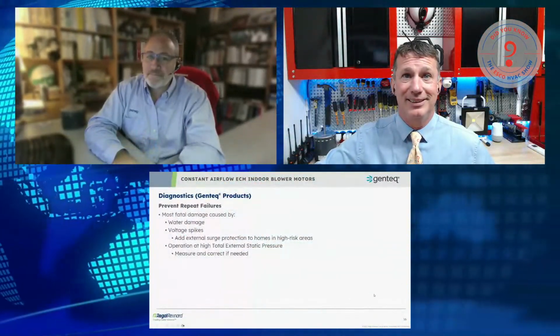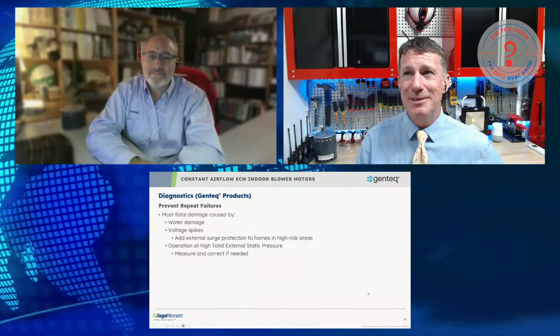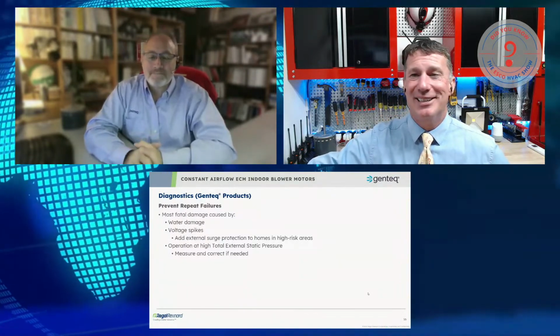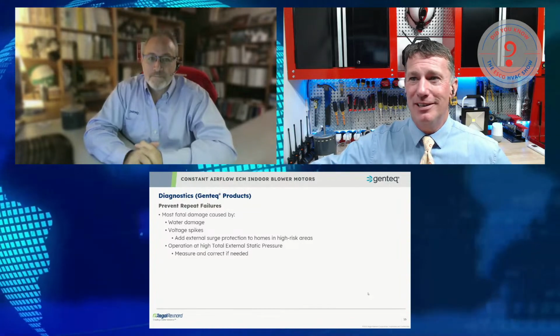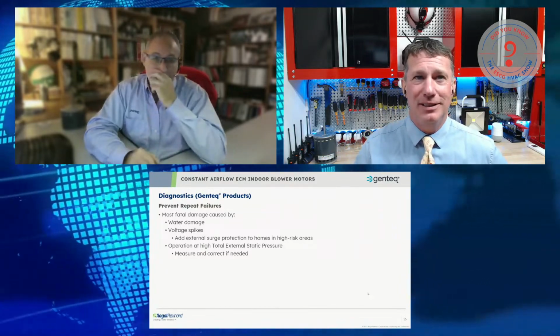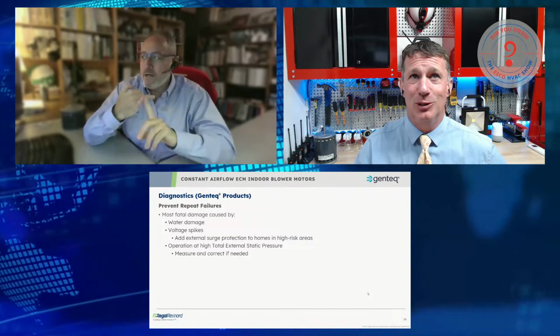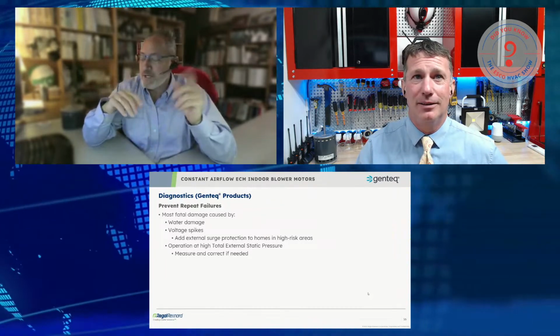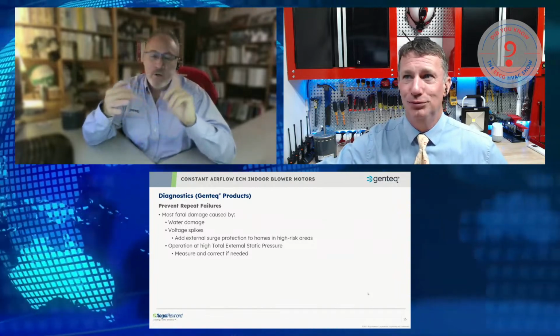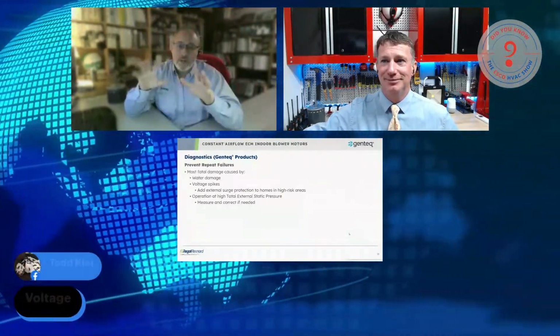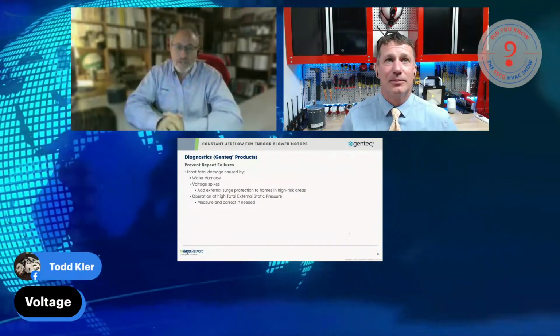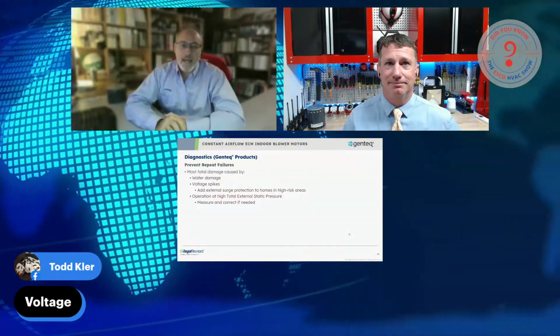But since we're talking about constant airflow motors, of the three items on that list, which one is probably going to be the most likely failure point? Let's pull some input in from those joining us today. So hop over there in your chat box wherever you're joining from and give us an idea. I can tell you what I've seen out in the field, but I'd really like to know. Is it water? Is it voltage? Or is it high static? And we could lump high static and dip switches together, because if the dip switches are set wrong, I'm going to have high static.